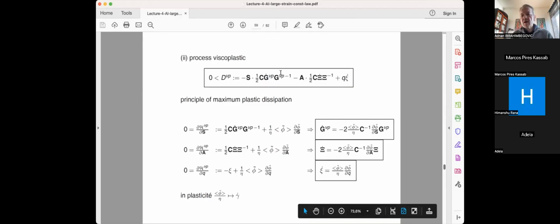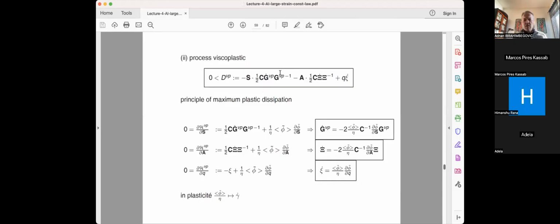So when I'm doing my, let's say, viscoplastic deformation, that means I'm going into the computation of viscoplastic dissipation, and I do that with a penalty term, where I assume that the yield function is used as a penalty term, and it's used only for the positive way, so it's 1 over eta times the yield function squared and 1/2 and so on and so forth.